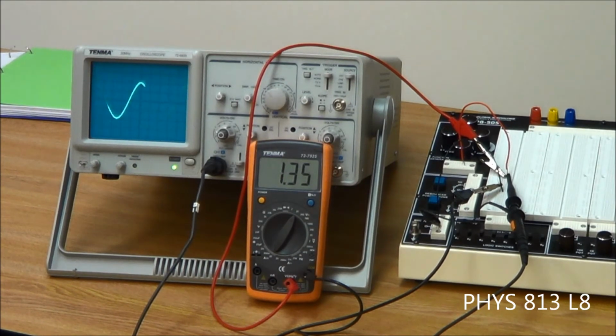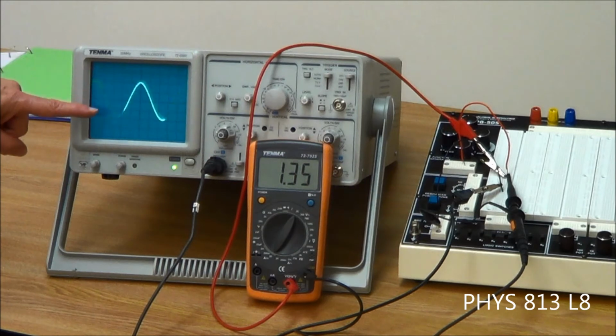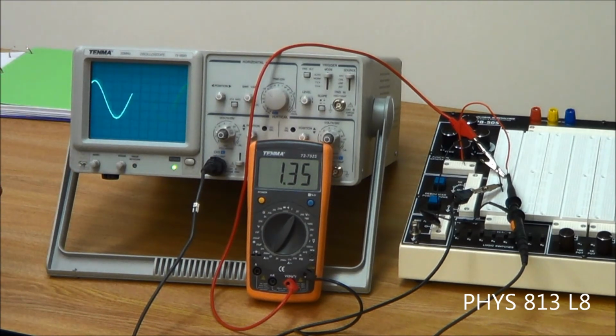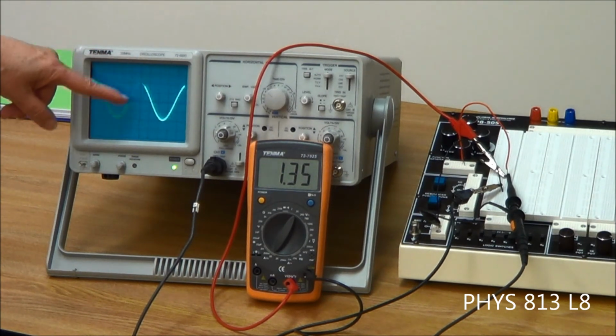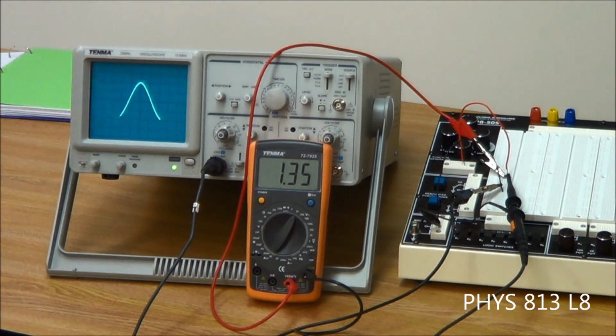You have 400 hertz. I would figure out the time and fill out that row, go through all 3 waves for the 400, and on the triangular wave and the square wave, you might need to change the amplitude just a tiny bit to make sure that it actually is the amplitude of 2 volts, or 4 volts peak to peak.